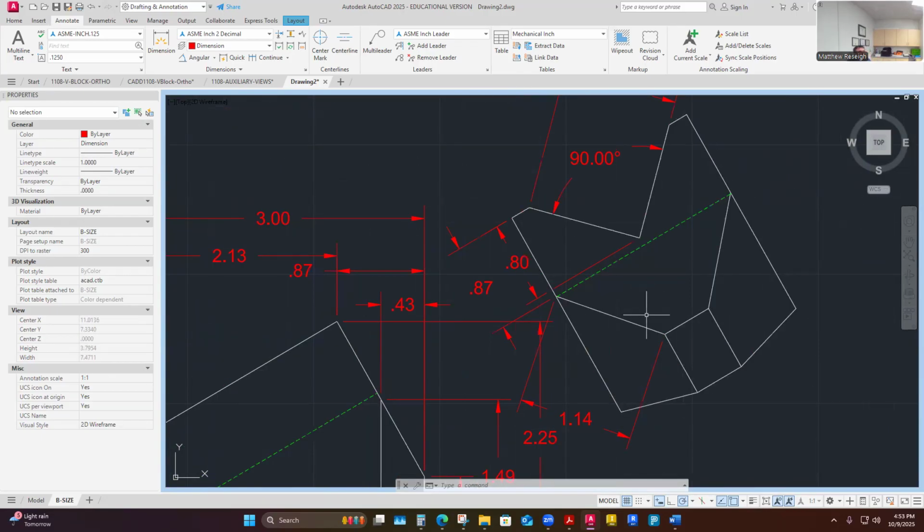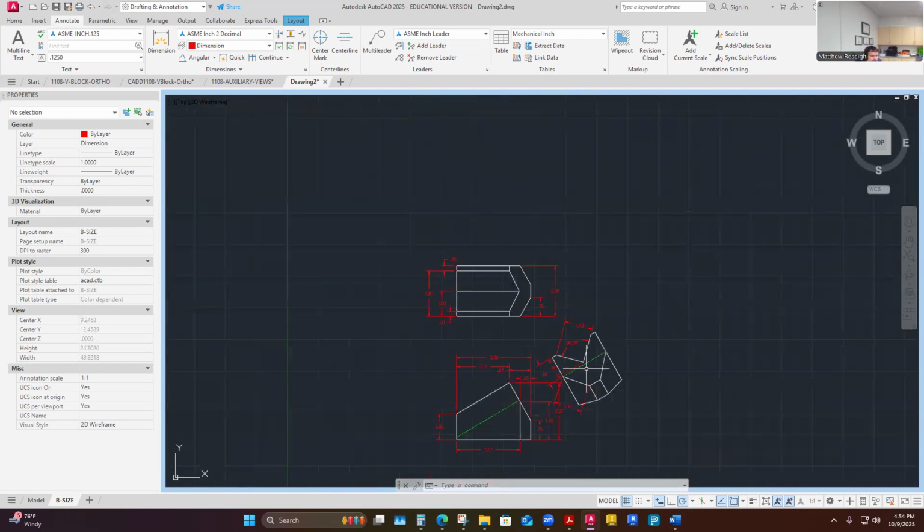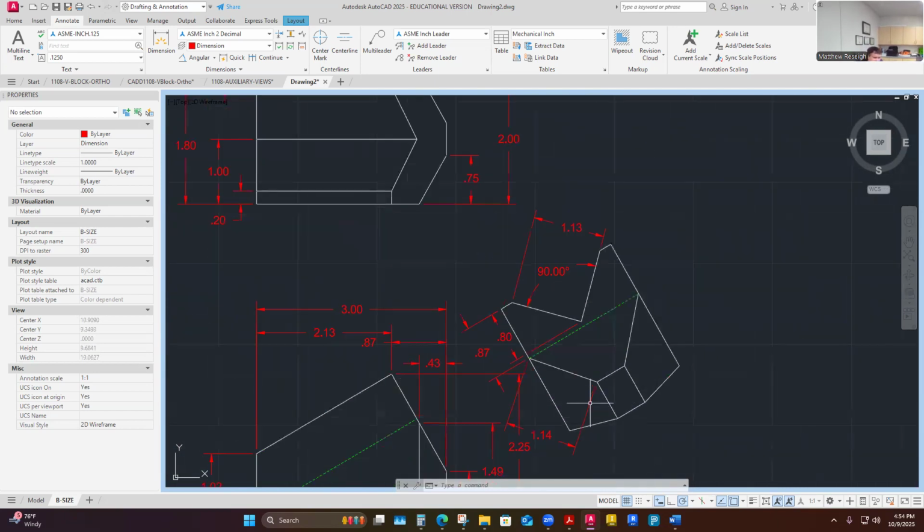Part is symmetrical from front side to back side, something like that. That minimizes some of my dimensioning, but it captures that, if I was to do a cutting plane line through from right to left across center, it would be a symmetrical part. And that allows some of these dimensions to be inferred, including in my general note. That's an idea.